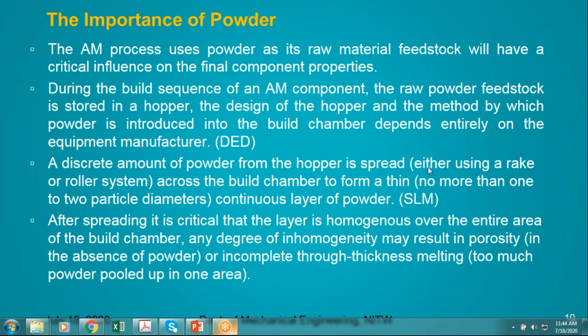Especially in the DED technique, multiple hoppers can be used for the production of functionally graded materials, or individual materials or alloy components can be stored in a hopper and fed directly into the build chamber through an orifice with the help of a pipe, along with the shielding gases, argon and nitrogen. For example, in the SLM technique, a discrete amount of powder from the hopper is spread across